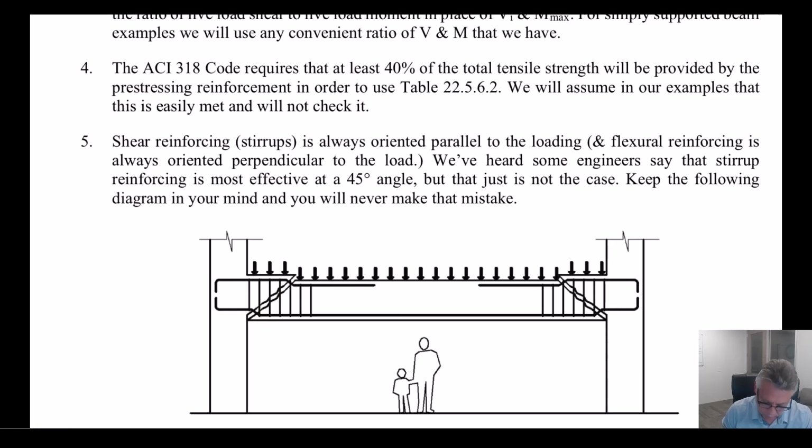We don't want to kink steel. Now, I kind of exaggerated that in this picture, but that's when bars start to rupture. Rebar's not meant to bend. It's meant to be axial. So that's how it works best. And I want you to think about this and understand that we're not making a mistake. It's not because it's easier to construct. This is what we want to see. This is how we want it to be.